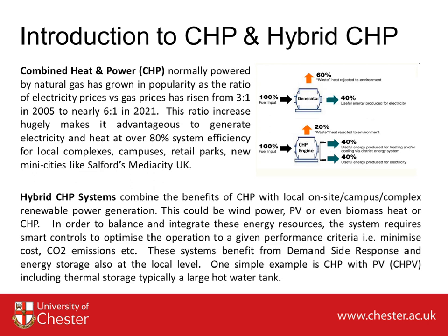One of the greatest problems for CHP is waste heat. And waste heat comes from the engine itself, which could be up to 20%. But also, it's enormous in poor utilization. So, for example, putting a CHP engine in an application where there's no need for heat would mean that you might generate that heat efficiently, but you'll lose it all because you've got no use for it.